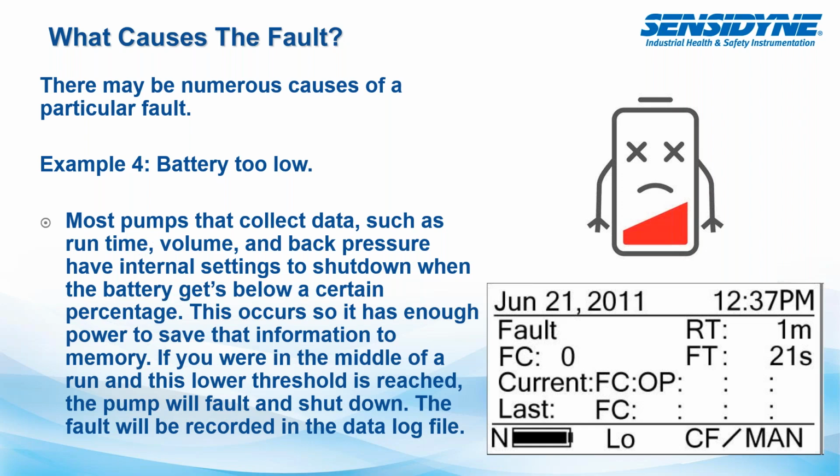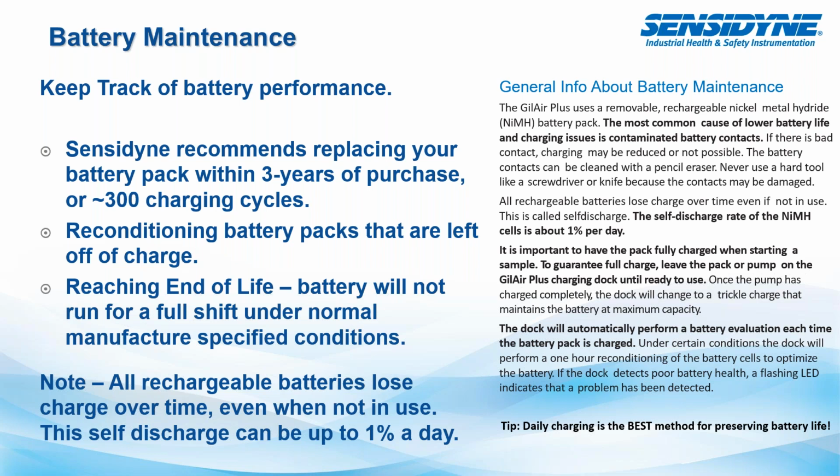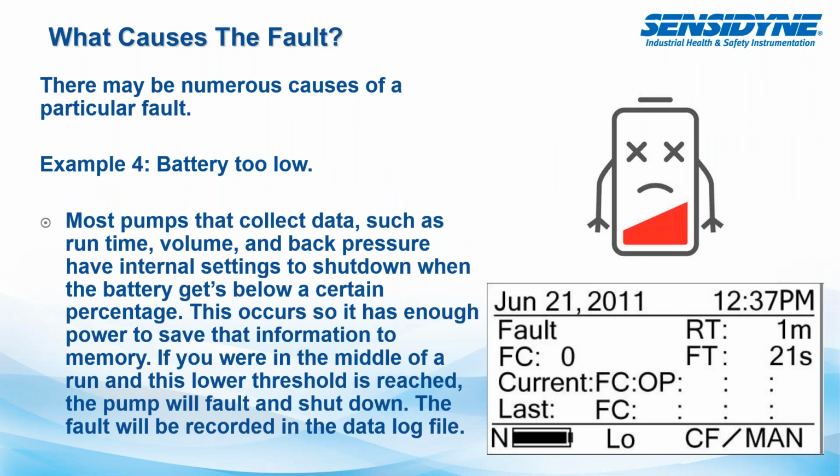But I wanted to talk a little bit more also about battery drain. For battery drain, the more the pump motor has to work, the more power consumption is utilized. So the starting projected runtime may be fairly large, but if you're getting a lot of load on your filter media, in order to maintain that same flow rate, the motor is going to have to speed up. This is like the RPMs in your car. As the motor speeds up, it's burning more fuel and causes that battery to drain a lot quicker. So that could be one of the causes of the quick battery drain.